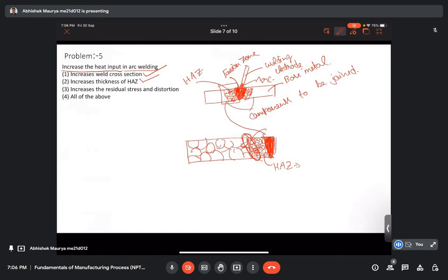In this region we will see the microstructures are not stable, or they are not strain free. Basically here we have smaller structures, and here earlier we had larger grain structures, and because of this heat affected zone, there will be a strain incompatibility near this region.